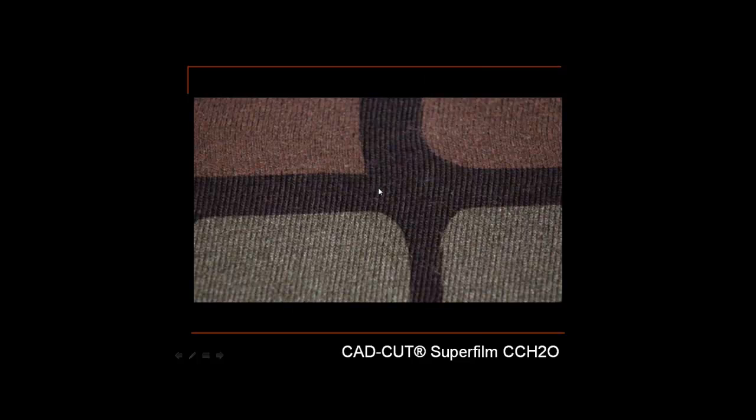And there's another close-up shot of the design you just saw previously. And so with this process, it's 400 degrees, 20 seconds, and you hot peel the backing, and basically just the ghost image of the material stays behind. And it's not 100% opaque, which means it doesn't block light or the garment from passing through. So the finished result is also going to be impacted slightly by the color of the garment.